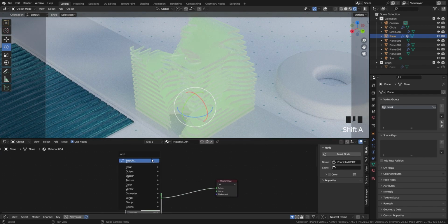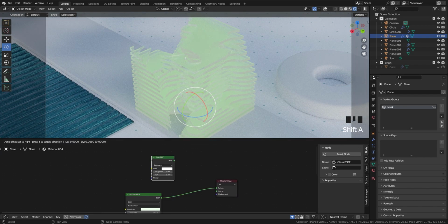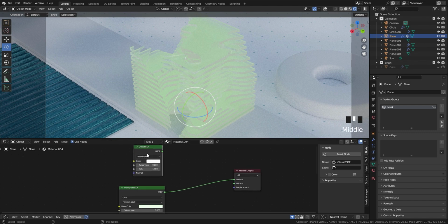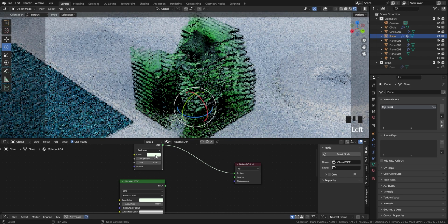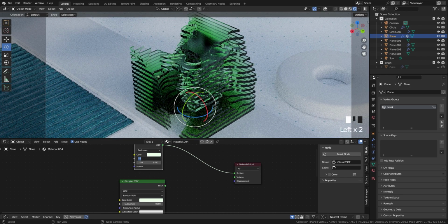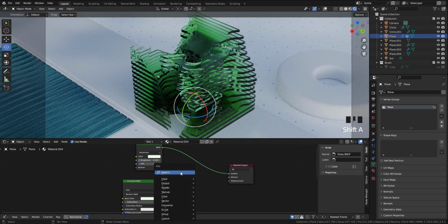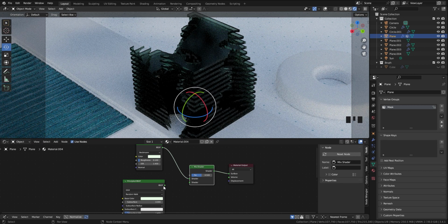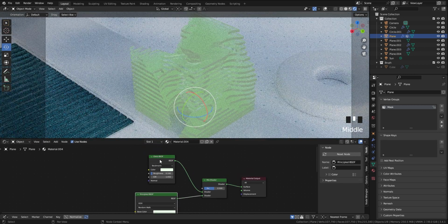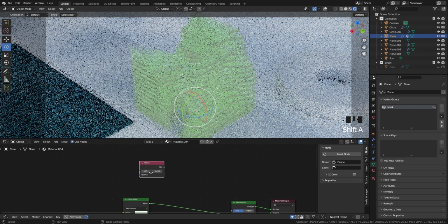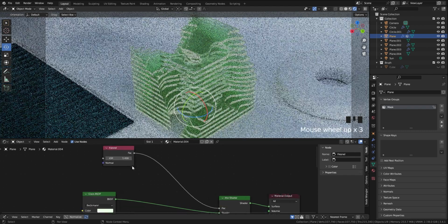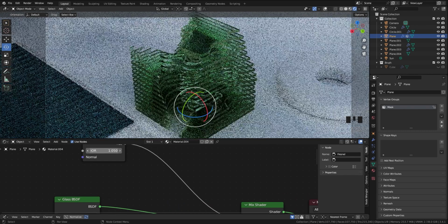And let's make another material, which is the glass BSDF. Use the green color that we made for the principled BSDF as the color of the glass and put the roughness about 0.1. To mix these two shaders, use a mix shader node. For the factor amount, I'll add a Fresnel node, connect it to the factor, and use 1.05 for the IOR amount.